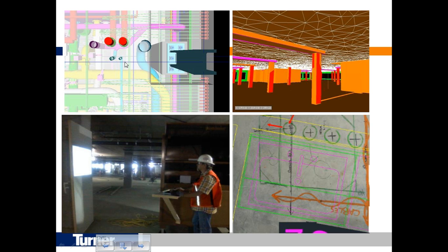In the upper left hand is an interesting one, and it really fits in with especially design and structural, where we've got a three-dimensional model here, but we've also got two-dimensional PT cables. And we started doing our inspections ahead of time. They were done almost 2 weeks ahead, where we had these sleeve locations and brought the structural engineer in and used our iBoards to talk about locations and how close they were to the PT cables.